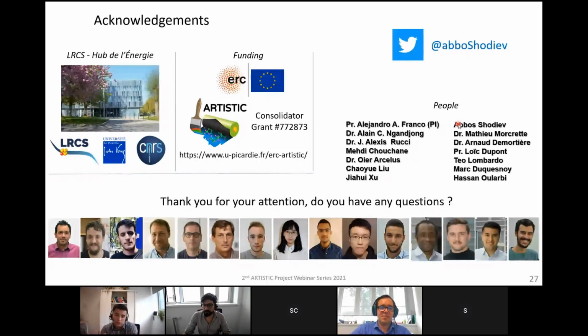You apply the force or vacuum with just air inside, then whatever air stays inside stays. Then you take out the applied force and put the electrolyte inside, and the electrolyte goes in due to the vacuum and soaks in. So this model can easily be divided into two simulations to represent this step.